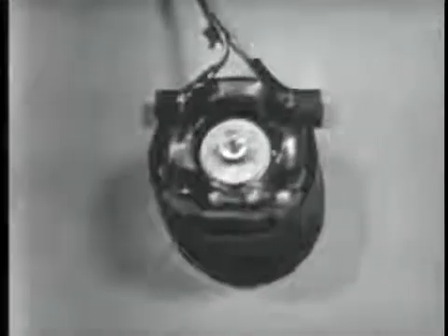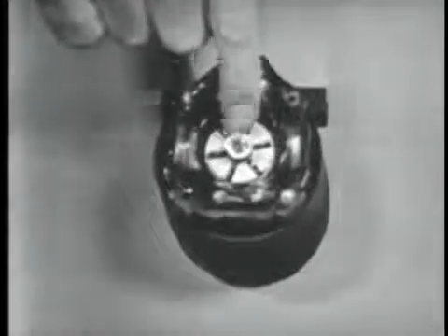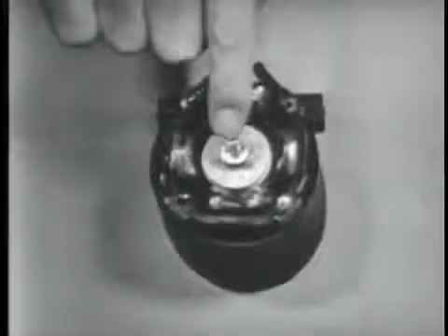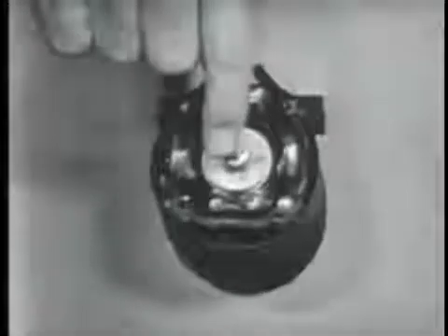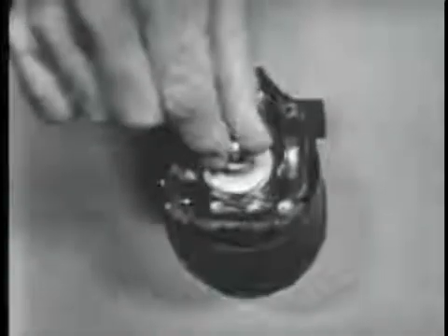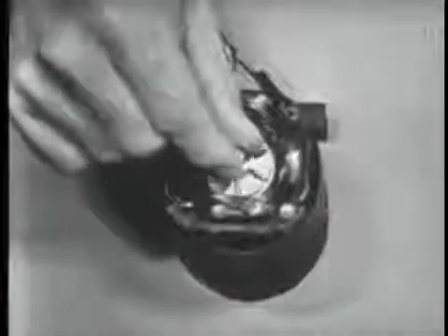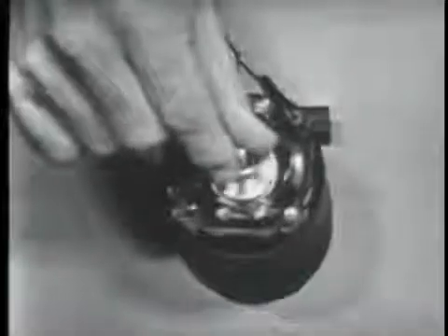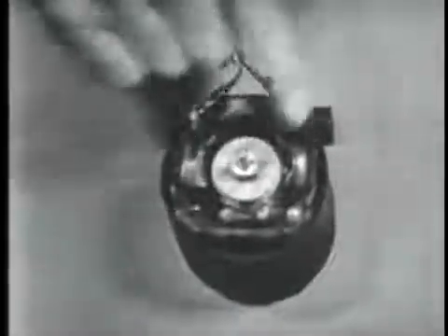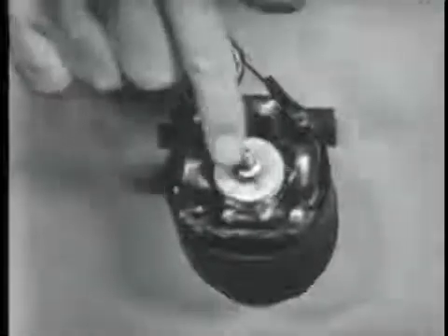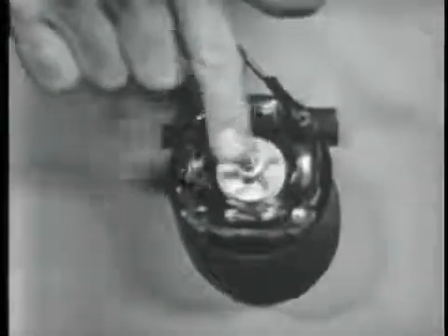Which brings us to item 5, which I believe you can have. Exactly. All right, the rotor of the induction motor does not rotate as fast as the magnetic field because of several forces that act on the rotor. One, the internal load, that is rotor weight, the little fan, the bearing friction, and so on. And the external load on the motor, such as the gears, pulleys, or the fan blade, or in this case, my finger. As I squeeze it a little bit, you can see that it turns slower. Right. That's work the motor must do. So the rotor's got to go slower than the rotating magnetic field in order to have relative motion so that it can become an electromagnet.